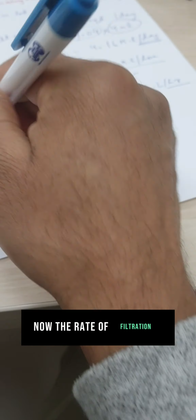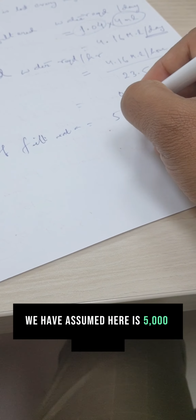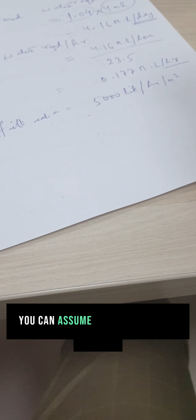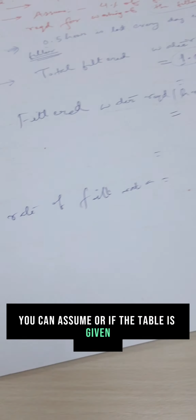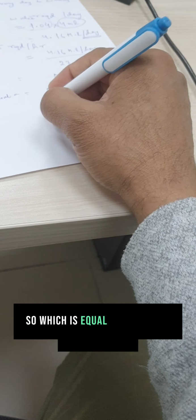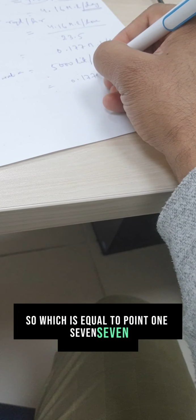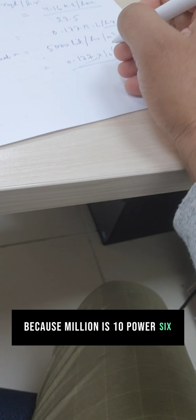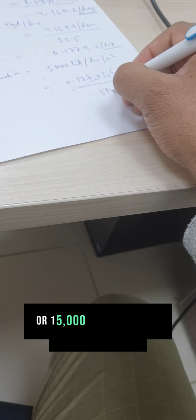Now the rate of filtration we have assumed here is 5000 liters per hour per square meter. If it is not given, you can assume, or if a table is given, you can take it from the table. Usually the rate of filtration for the rapid gravity filter is higher than the slow sand filter. So the area is equal to 0.177 into 10 to the power 6 upon 5000.